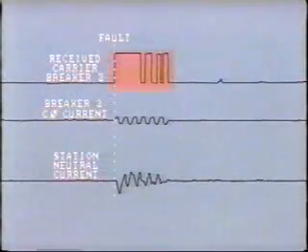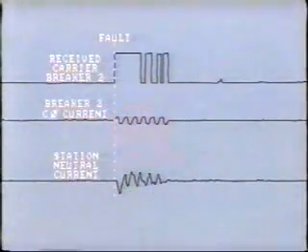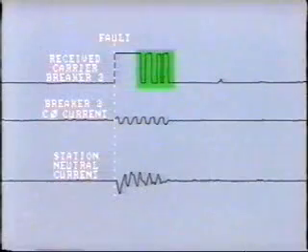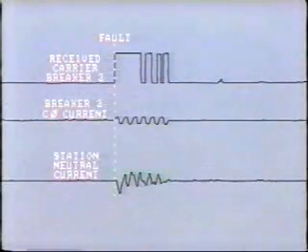Here are traces of the carrier signal that was transmitted from breaker number 2 during the fault, and the C-phase current seen by breaker 2. About 3 cycles into the fault, interruptions or holes begin to appear in the carrier signal. The holes are due to the extreme distortion in the station neutral current, that is, the reference current. How is this?